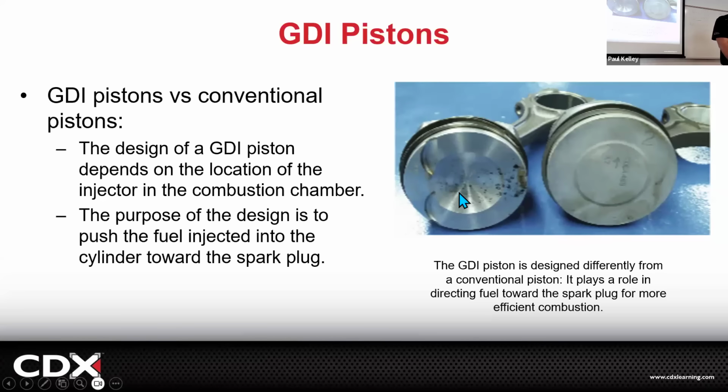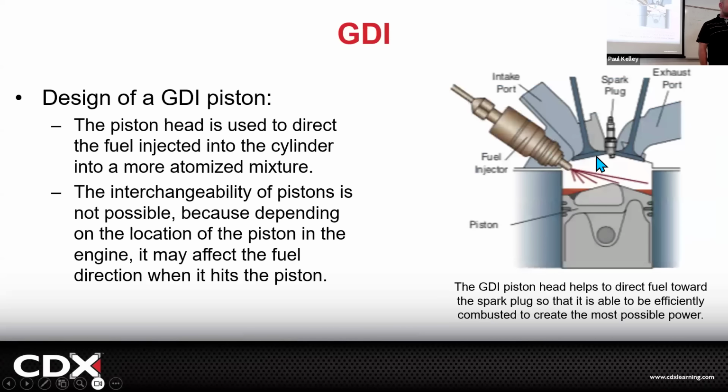Cool. And then they can also have valve recesses, because if we're going to hang that valve open longer, we need to make sure the piston doesn't come in and clip it. So this is a modern Atkinson cycle GDI piston. This is like a port fuel injection, Otto cycle, typical 4-stroke piston. Cool. So just a little bit different, and they can be different styles too. They could vary, but you can't interchange them. So you can't be putting old school pistons in the new school or new school pistons in the old school. It's not going to run right.